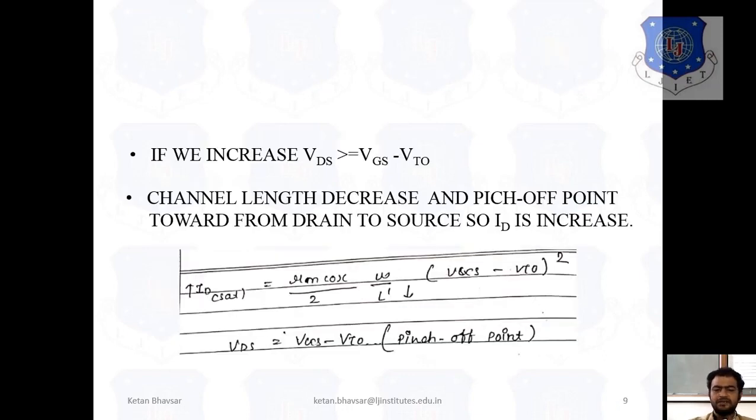So if we increase Vds to be greater than or equal to Vgs minus Vto, as you can see, your total channel length started from y is equal to 0 to y is equal to L. Now instead of L it becomes L dash. So in channel length modulation, we have the same equation for the drain current ID in the saturation region, but instead of L we have to write L dash. This is the only change when you write the ID equation for saturation in channel length modulation.